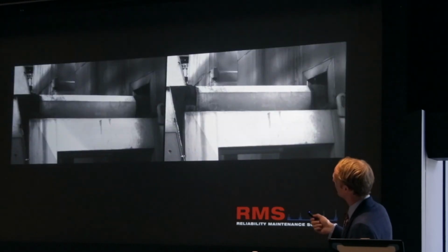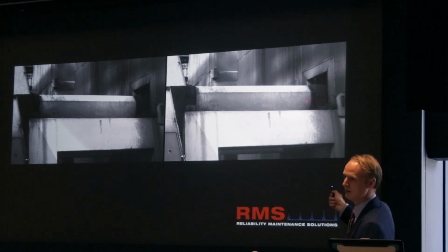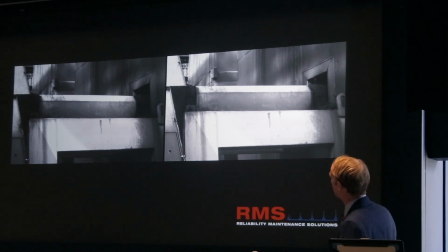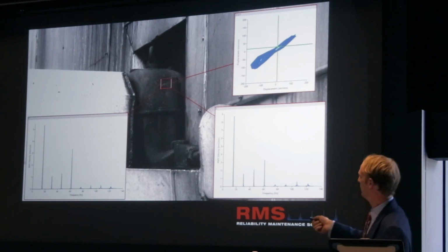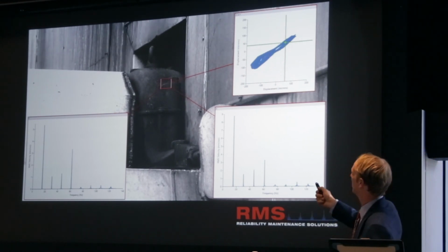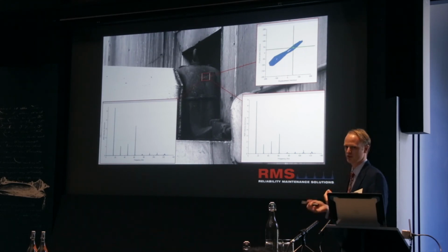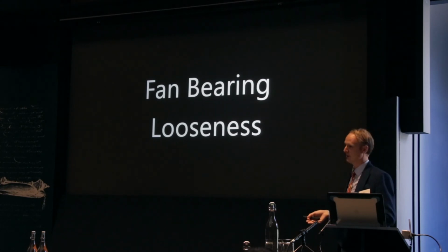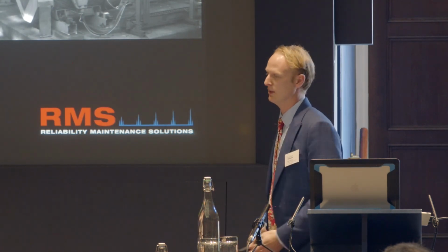And you can see the whole structure is vibrating. And here's the fan behind here, and you can see the bearing massively moving around. So I'm able to then show this video, instead of using the traditional graphs, the spectrum and the orbit plot there, which are just numbers and go straight over most people's heads. I can show them a video and they can see the damage that's being caused, and it helps them to get an appreciation and to act quickly.